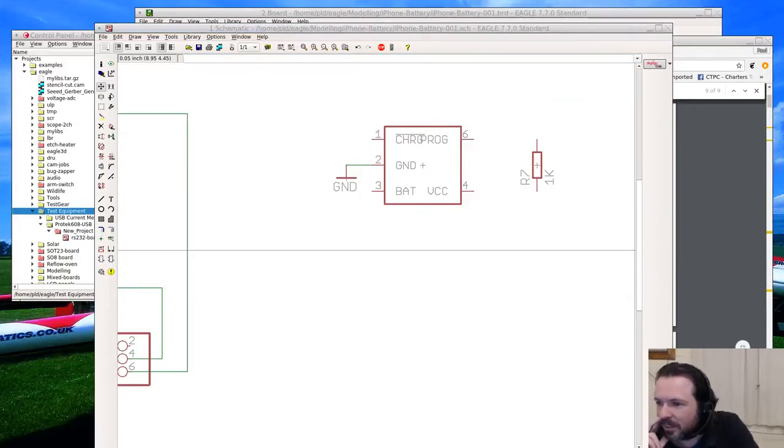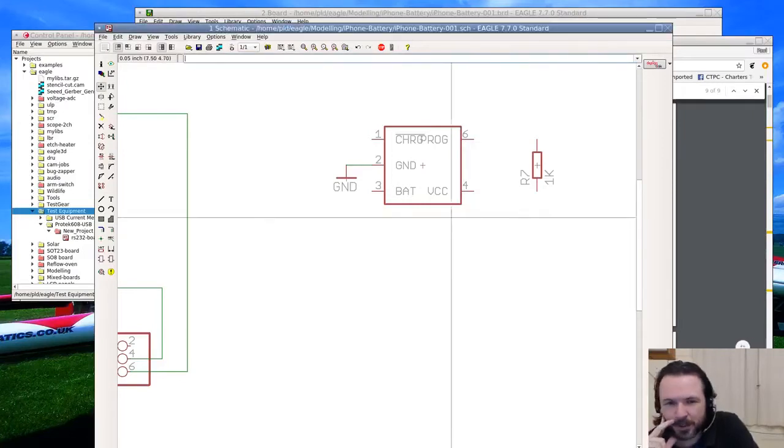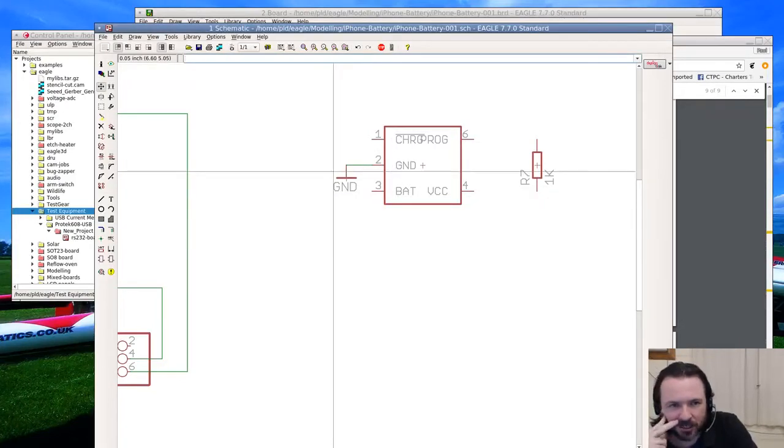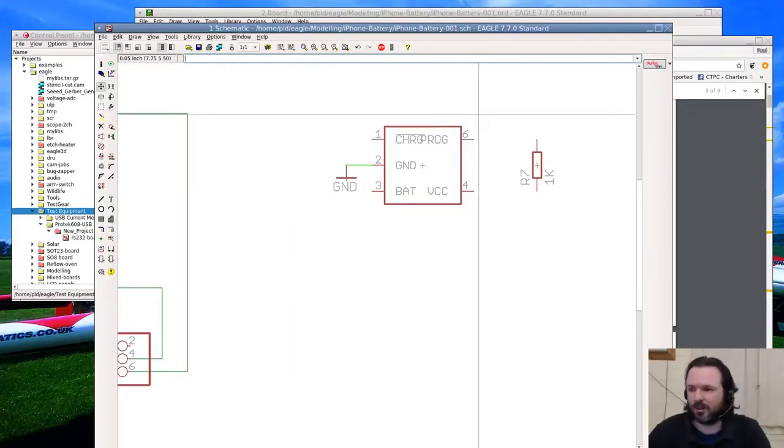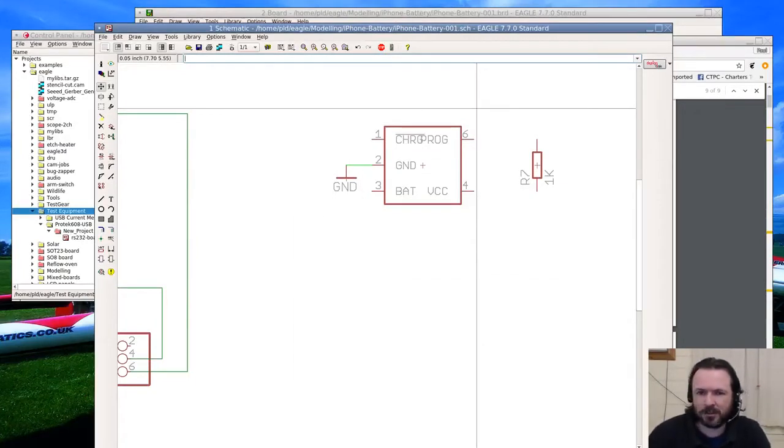Hey, Marley. Yeah, Spencer, actually I think that's where I use the Linear version, because the Microchip one doesn't really do a very good job down below about, I think it was about 50 milliamp hour packs. And then the Linear one, however, was good for any up to about 150 milliamp hour packs.